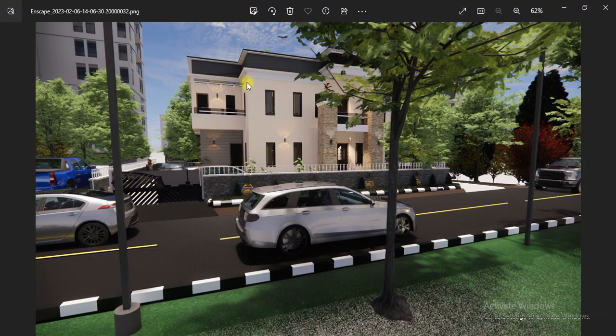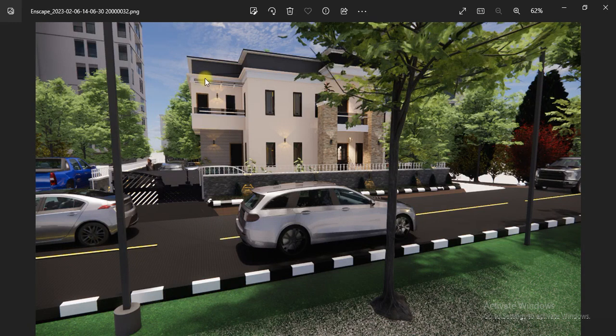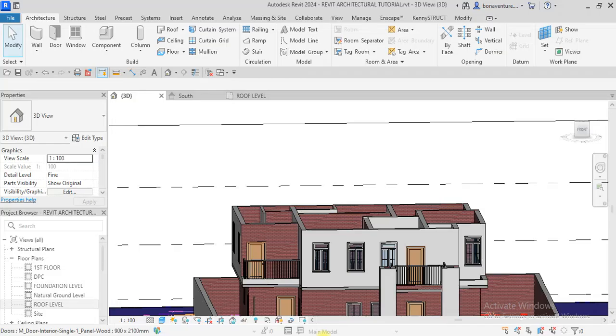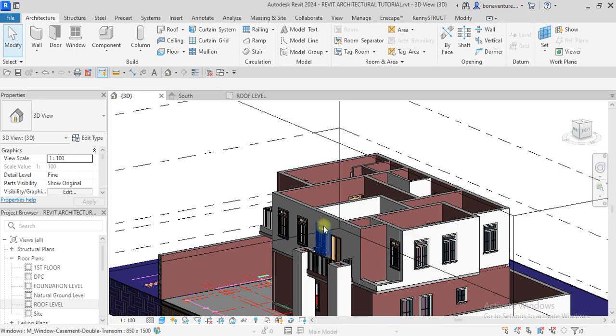So just as we have here, this is the roof and where my current wall ended. This particular wall ends here. In this case, this is where it ended. Now we have this extruded wall element. This extrusion, we have this extrusion here, you understand, after which we will now have a continuation of this parapet, you understand. Okay, so let me first of all create that extruded element on the wall. So what I will now do, for me to create this, I have so many ways